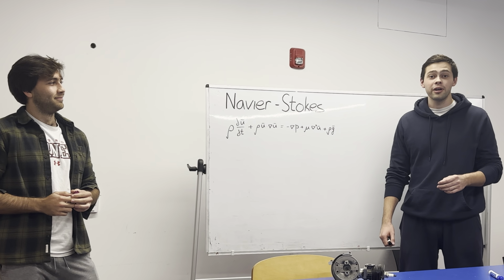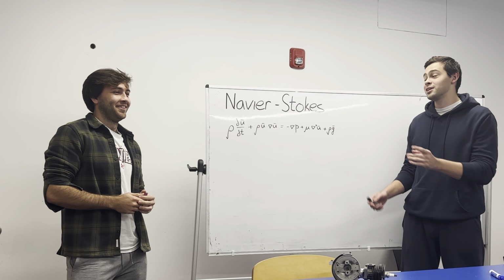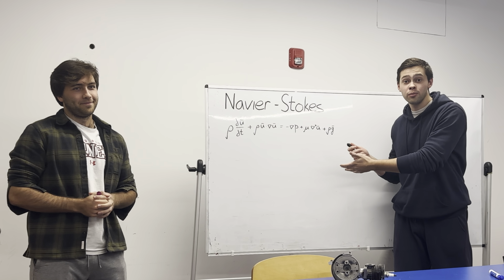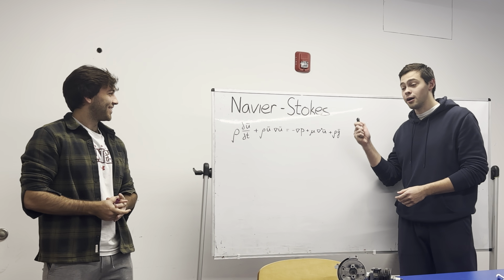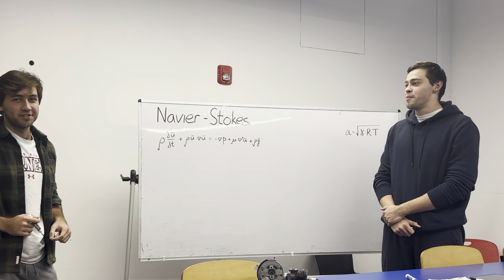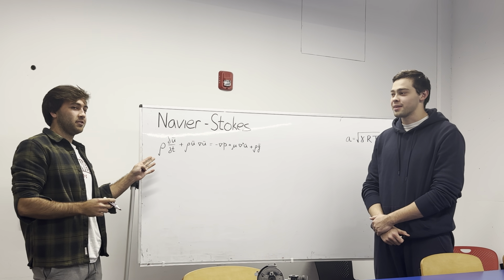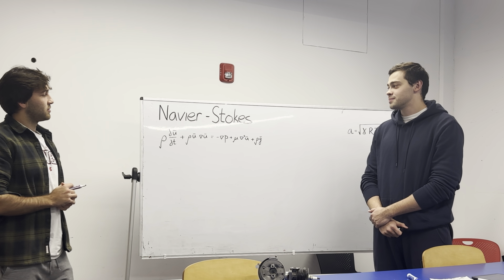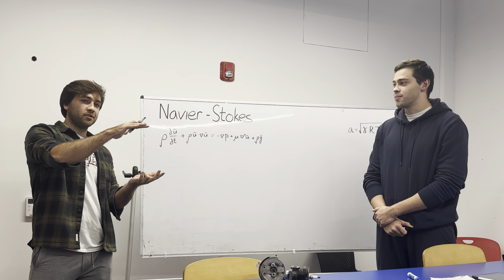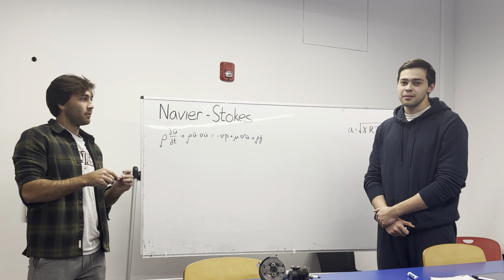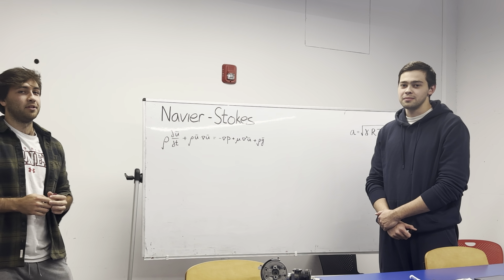For analyzing the lubrication flow around our cylinder, we'll be using the Navier-Stokes equation. This equation effectively is the conservation of momentum equation that also takes into account the viscous term. So for the Navier-Stokes equation, we're going to make some assumptions to begin. First, we're going to assume that our flow is Couette, which means it's velocity driven, as well as the fact that our flow is unidirectional. So we'll have no velocity in the y and z directions, which means our gravity term will cancel.